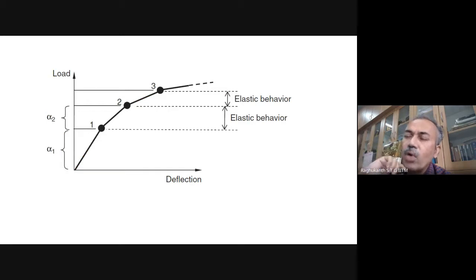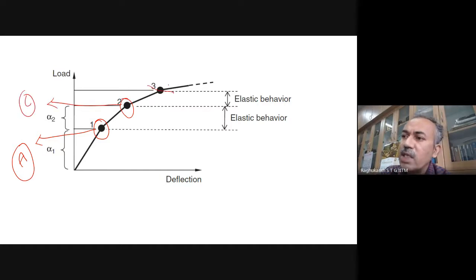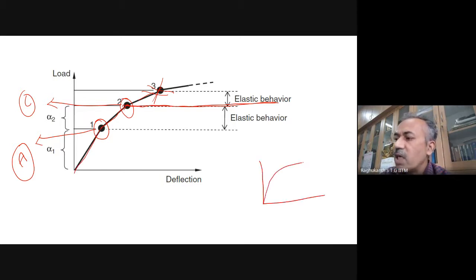Now here, one most important thing you have seen in this problem is that the first hinge has been formed at A. Now the second hinge has formed at the C point. There is no third hinge in this problem. So automatically it has become something like this. So the most important assumption here, as already told, is about the stress strain curve, so the moment versus curvature is basically curved actually.